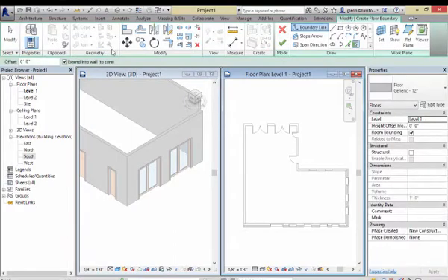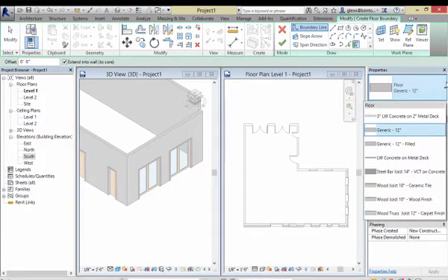It'll become more important when we start talking about structural modeling. And now we have, again, this notion that there's always a type and some information about how it should be placed. So types, let's take a look at that. We can put a nice generic 12-inch floor of some mystery material in there. We can put in a 10-inch joist floor that has ceramic tiles, or a 10-inch joist floor that has wood finish. And again, we can change these types. If it turns out we need smaller or taller joists, or a different finish on the floor, we can do that too. And because it's types, anything that we place, we can change the type of later if we decide we want to make it something different. So there's always a type to the geometry.